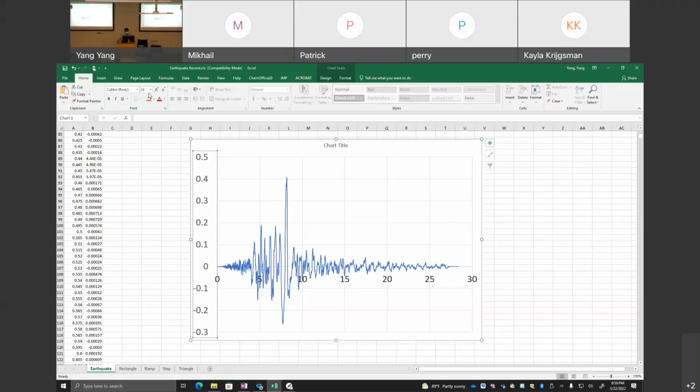So when you input this acceleration record as a force, you need to multiply the number by the g value. You can use g either in metric units or in imperial units. Anyway, you should multiply so that you get the exact acceleration number, rather than the ratio to the gravitational acceleration.